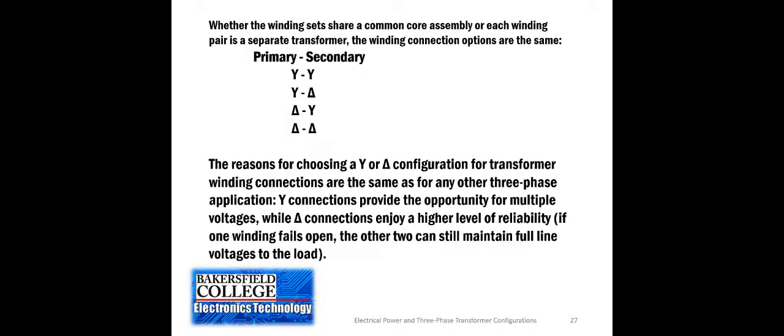And that helps out really well because a lot of times these transformer units are multi-purpose. They will have different taps that you can use to create exactly the voltage range you want, depending upon what the voltage coming into the transformer is, but also by changing whether the primary is a delta or a Y and the secondary is a delta or Y, you can further get a different set of voltages. So that's good.